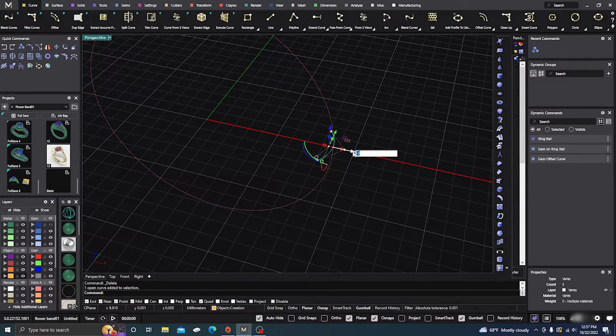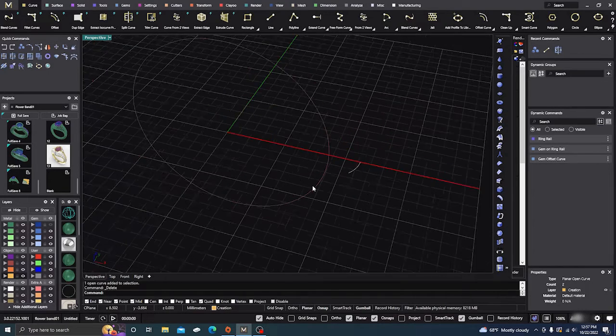I'm going to offset it about 2.5 millimeters or so, and then I'm going to select a curve and draw it from that quad to the midpoint there, select that and split it with this. Alright, and then take that and just delete it, and take that offside there and delete it.